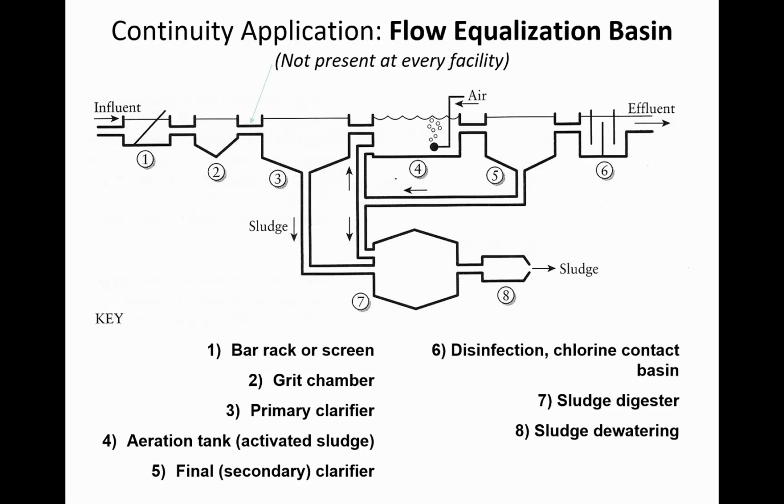It takes several weeks to get the bacteria conditioned and operating in sufficient number and at the right temperatures so that your treatment plant is really removing efficiently all of the pollution that's needed. So a pretty common thing is to put at the head end of a system like this a flow equalization basin to even out the temporal variability in water that's coming to a sewer plant.